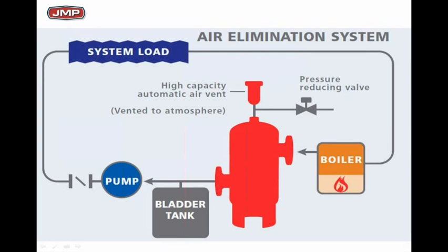We have it under pressure. We pressurize the bladder tank. Therefore, it runs quite well, but make sure you understand that this is a great system, and it's probably 90–95% of new projects are going this way. So a little fine note would be try to avoid putting the bladder tank directly under the pipe or directly over the pipe. We don't want trash plugging anything up, and we don't want to have an air pocket trapped there. So that's kind of the reasons for that.